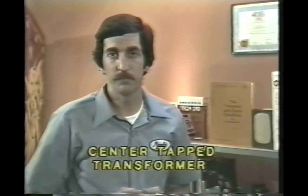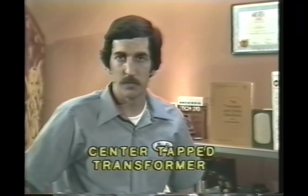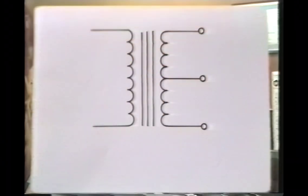It's called the center tap transformer. When the transformer manufacturer is making the center tap transformer, he'll start winding the secondary and he'll stop exactly halfway through. He'll pull a loop of wire out and attach a small lead to it and then continue winding the secondary. The voltage between the center tap and one side of the secondary is the same as the voltage between the center tap and the other side of the transformer secondary.